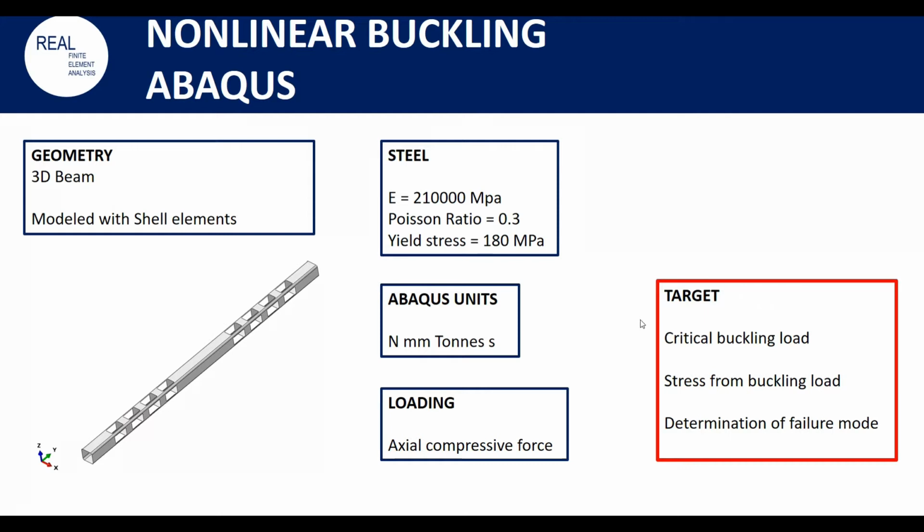So to do so, the geometry used will be a 3D beam which will be modeled with shell elements. Material will be steel with these properties. Abaqus units are Newton, millimeters, tons and seconds.